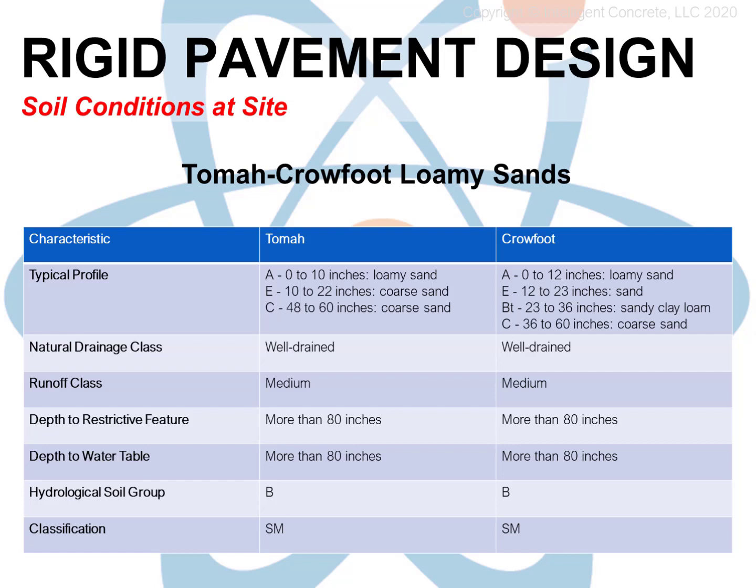You'd have thought that the USGS, the USDA, the USCS, and AASHTO would have talked with each other, but I guess not. As soil engineers, we deal almost exclusively with the Unified Classification System. Highway engineers use AASHTO, and agricultural engineers, also known as farmers, use the USDA methods.